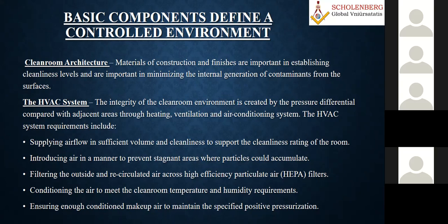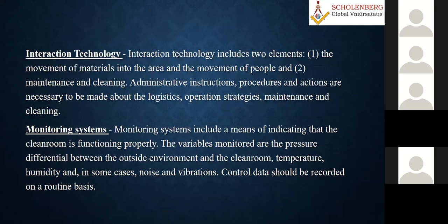Then as much as possible, use filtering when you are taking outside air or recirculated air. Before that, you use all types of other filters so that the life of the HEPA filters will increase. The pre-filters and all the other things will definitely help you to prevent this. And makeup air, specified positive pressurization. This I told you, all clean rooms are at positive pressure.